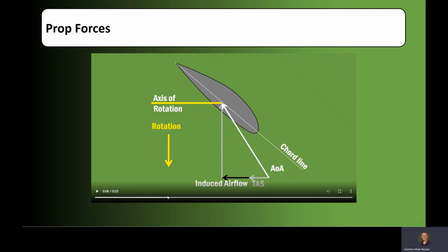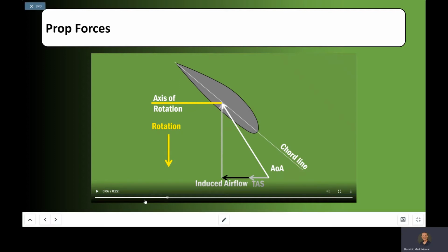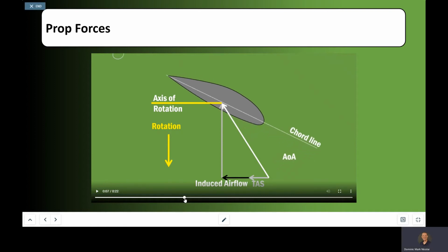And if I want to go faster, I just start pedaling faster again. And it gets to the point where I'm pedaling so fast I'm not getting any faster, but I'm working really hard. So you shift gears to a larger gear. Or in the airplane, we would go to a larger angle of attack. And you would keep that process going so that the faster you got, to help maintain the most efficient blade angle, the blade angle would be adjusting itself.